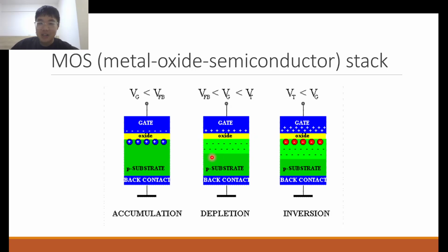So this region over here that's in light green now becomes a depletion layer, because there are no more free mobile holes anymore. It's only fixed immobile negative charges. So it's a depletion layer, which is unable to conduct electricity, so it acts also like an insulating layer.